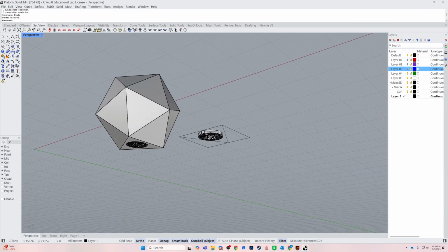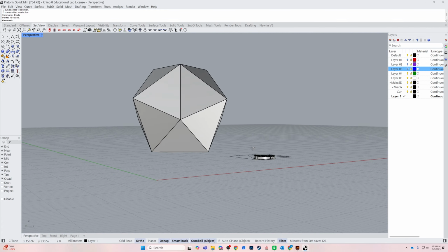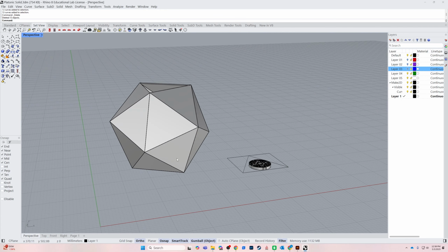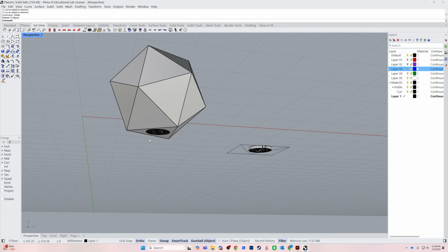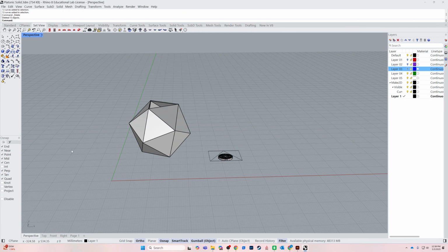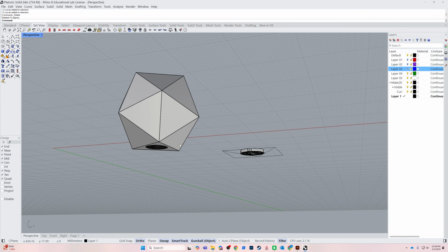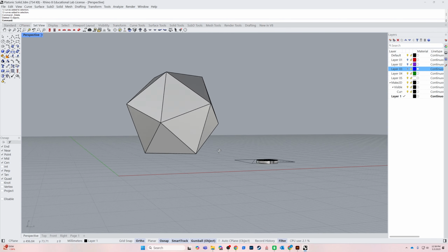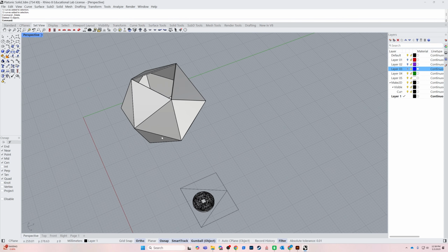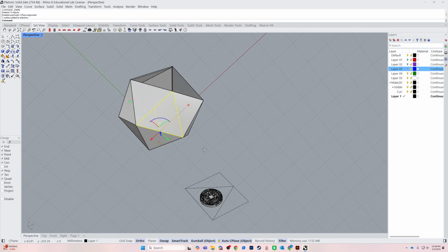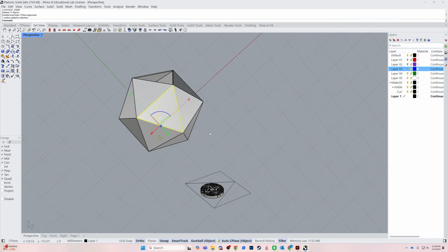So what I'm going to do now is rinse and repeat that for each one of these faces. I'll do it one more time here, and then I'll do it kind of sped up so that you'll see what I'm doing. So again, go to another surface, and you can pick any surface you want. Say I want to do this one. Make sure my auto C-plane is turned on. Control-Shift-click here. That has now created the C-plane onto that object.